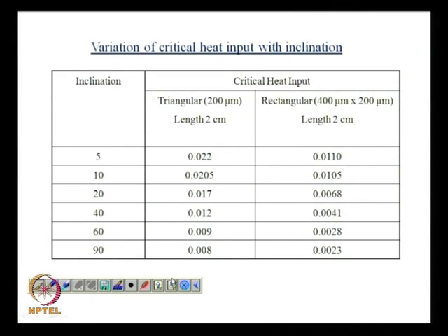What I would like to mention here is that even though the corners should be such that there will be liquid evenly distributed at all corners, inclination will still have a role to play, because if you incline the heat pipe, then there would be an opposing body force acting on the flow.